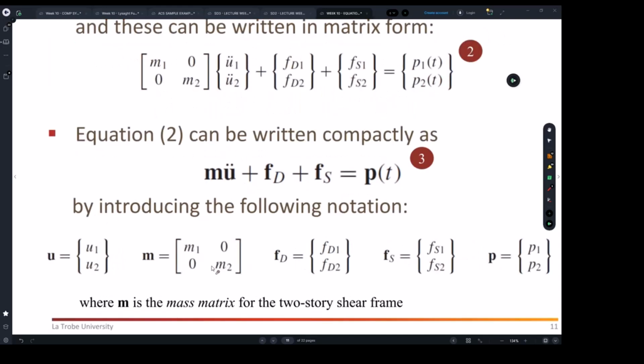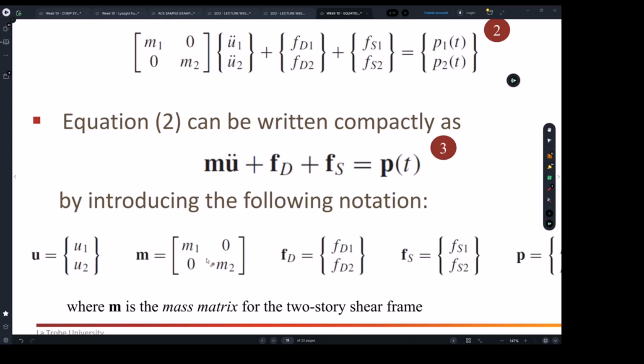Now, with the mass, you don't need to do any. We know mass. We got two floors. One is level 1, one is level 2, and if you want to establish it in a matrix, because the mass is not in function of the stiffness, it's just a property for the floor. The mass is not in function of the column's stiffness or damping. They can sit like this.